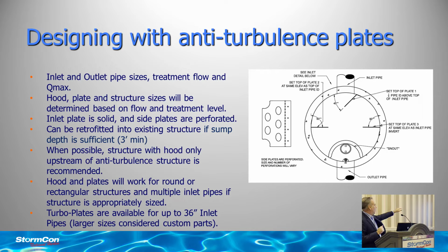So we're basically going to figure out the size structure we need, the pipe size that we have, the flow that we need to accommodate. And then we're going to talk about the modeling and how we use that a little bit later. But we basically need to fit these components inside the stormwater structure with the hood always being over the outlet pipe, okay? And there's going to be a sump in the structure.